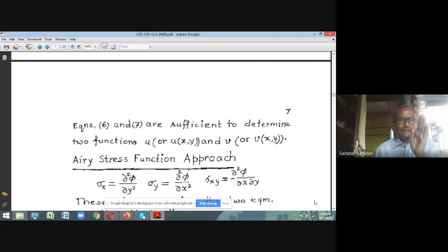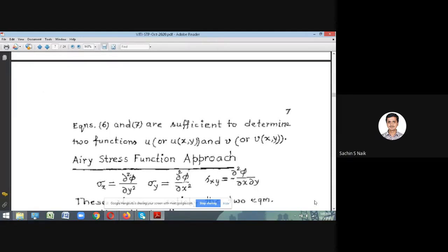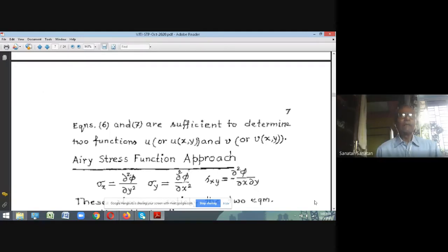The section C is going to move by the same amount, whether it is lying on the left segment or the right segment. So the same displacement occurs at that point, whether it is lying on the left segment or right segment. This is the compatibility condition. Is that clear? Sachin, can you give me feedback? Is that clear? Yes, sir. He says yes. Okay, good. So that is the compatibility condition.